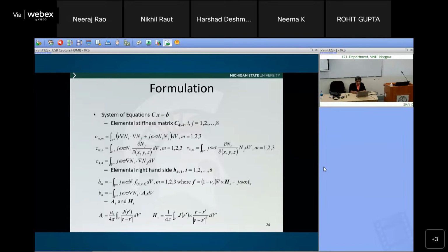So what I need to do is compute AS. I can use the mesh, any arbitrary coil geometry, which I'll show some of these in the afternoon, and numerically integrate, evaluate this integral. So that means the source field is known. I don't have to mesh it. Once I've done it, I have the field calculation. I just use the field, wherever the coil is going to be.